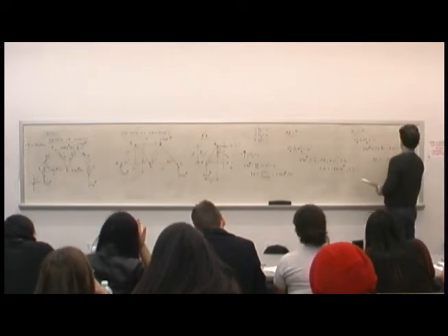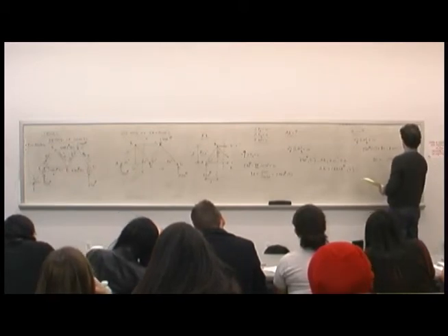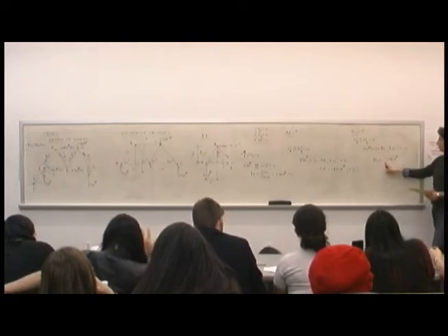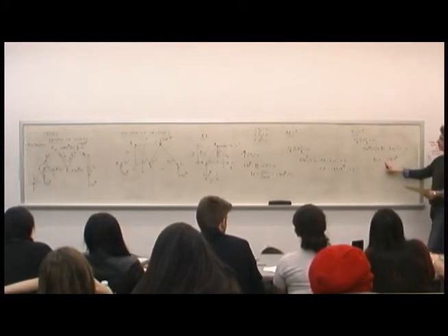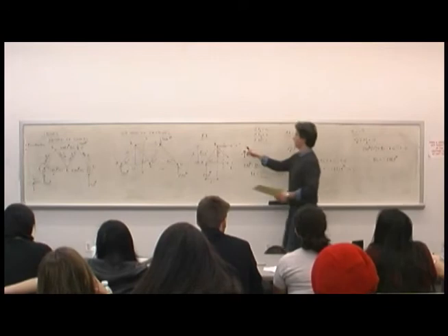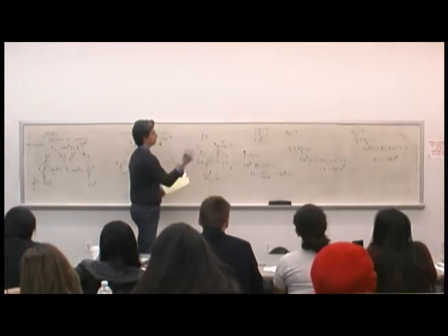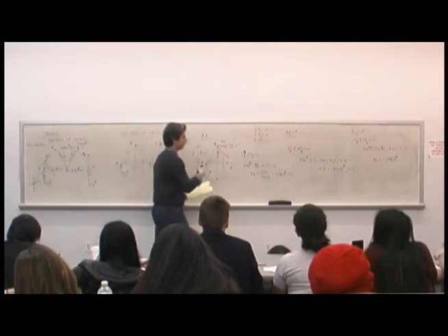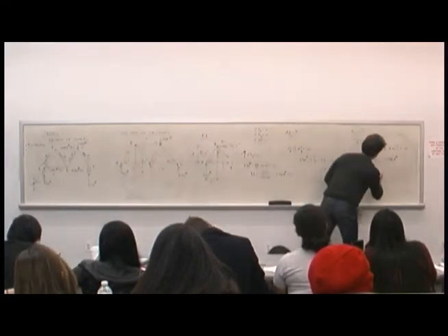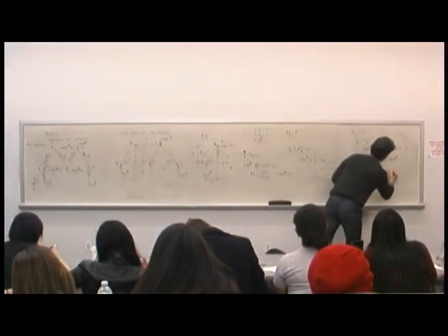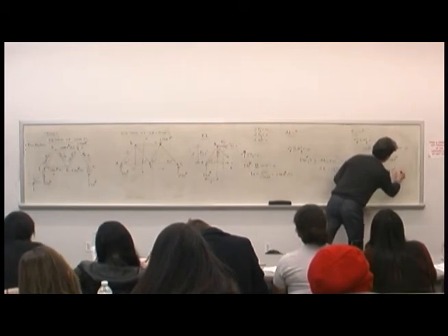Yeah, I have 288.7 pounds. So, because it's negative, what's the deal? What's going on? Right, it means that this direction is not right. This direction is going the other way, which does what? So it's in compression. So BC is equal to 288.7 pounds in compression.